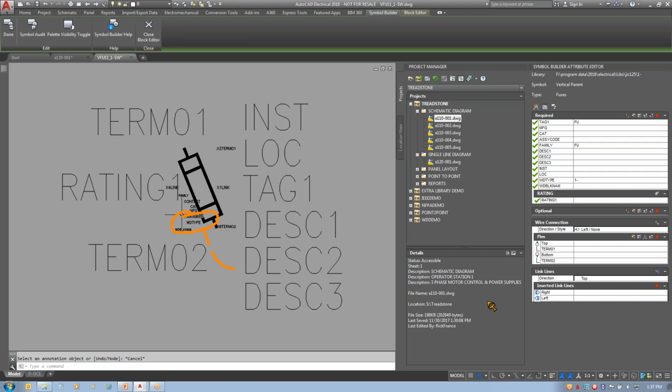This is the attribute that does the magic. You can see it's one of the required ones that needs to be in here. So it came over from the template. Since I used that template, it was okay, but I could literally take a normal schematic symbol, add that attribute, set the value to 1-line, and it would be a single line component as far as the software is concerned. But that WD type is what tells the software this is a 1-line, single line component.